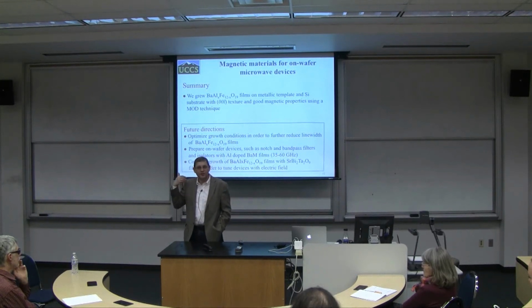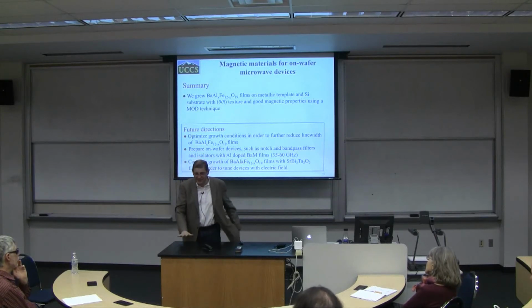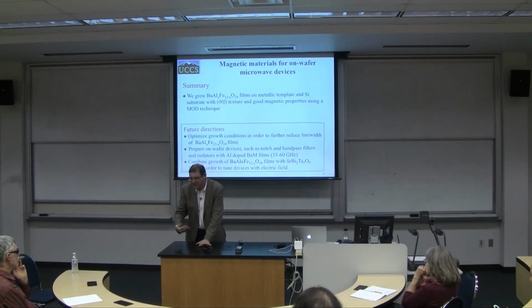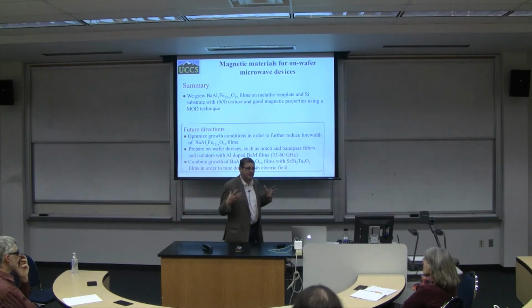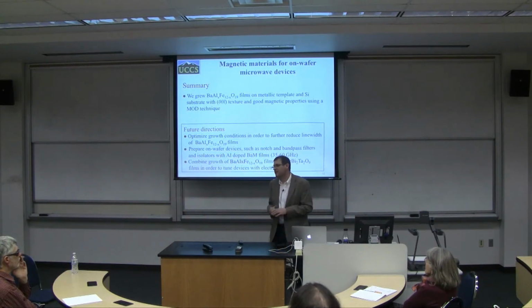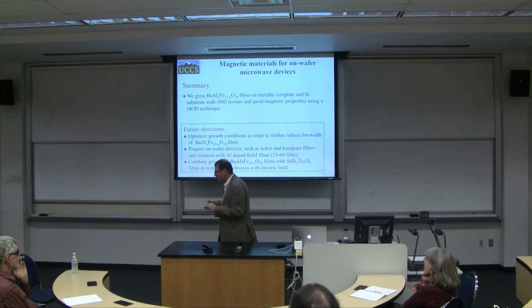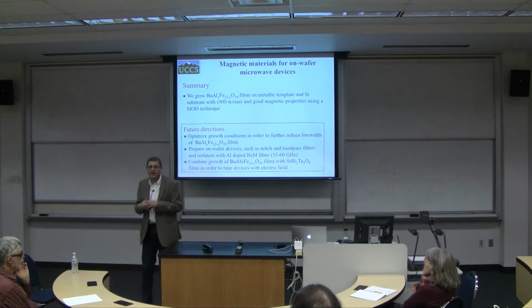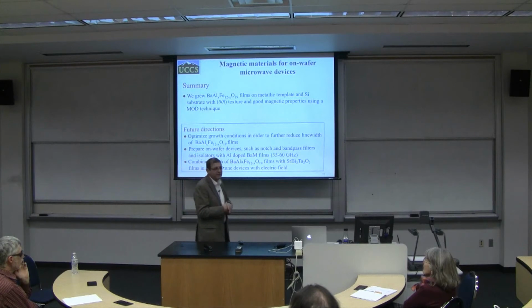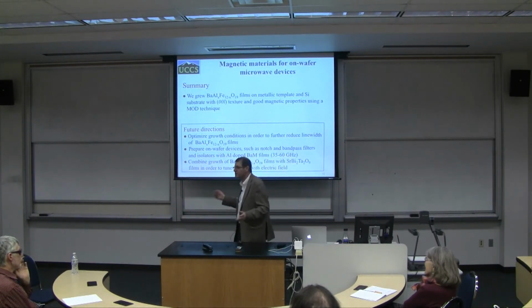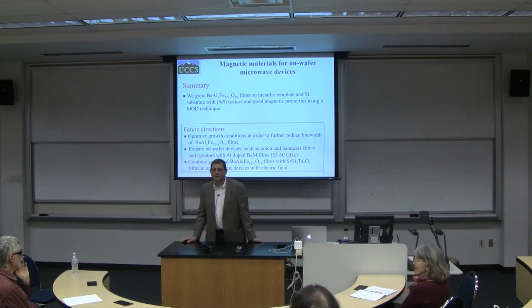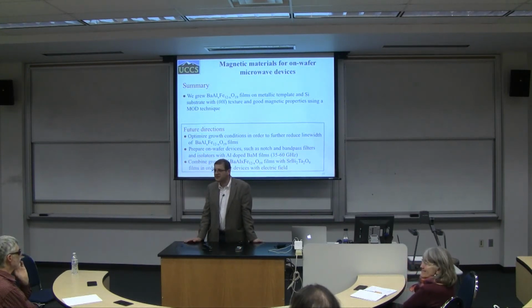In other words, if your metallization layer is not very good, it doesn't contain the wave. It's basically letting the wave leak out, which is bad, because then you have losses. So all these things have to be taken into account when you are designing the system. But the only thing you can come up with so far is platinum. I don't want to go to other very exotic materials like ruthenium or osmium, because they are even more expensive. Any other questions?